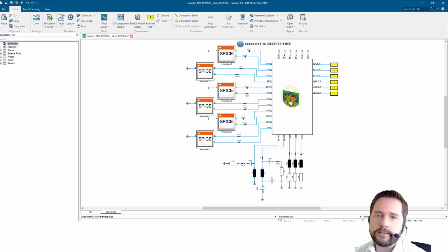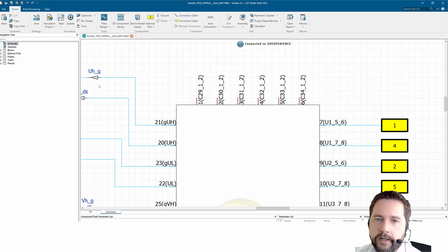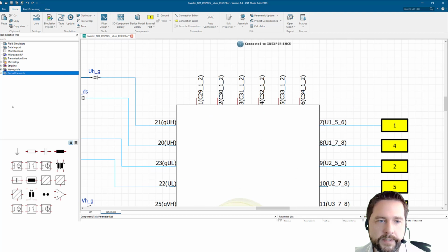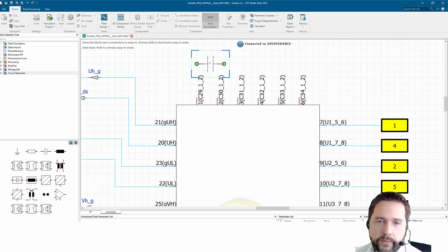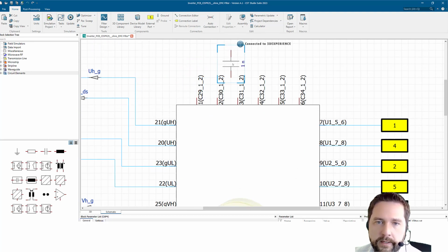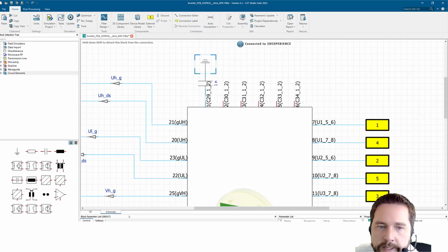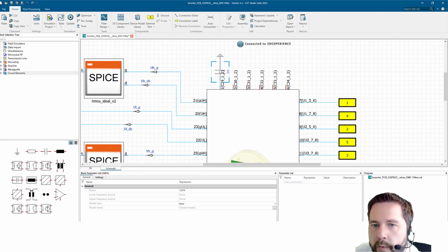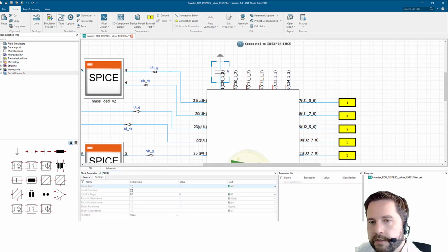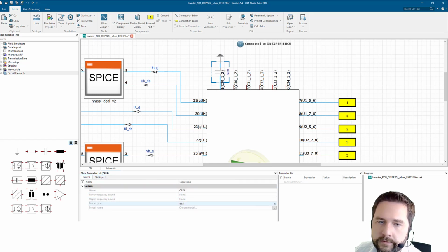We are adding them as ports, and then in the schematic, we can put the capacitors in with parasitics, so we can also consider the ESL and the ESR in the simulation, and that way we can simulate different constellations of X and Y capacitors for the DC filter we are building here.